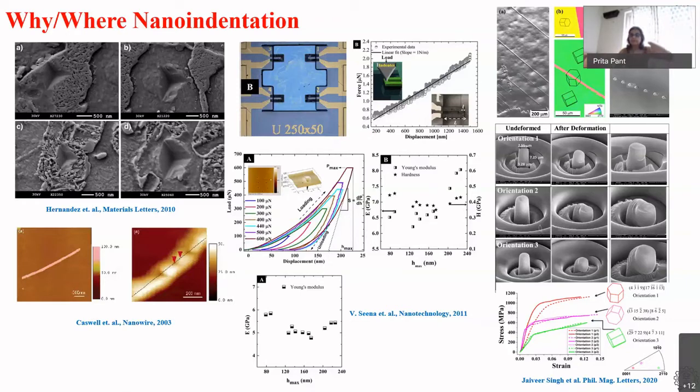film of it. Now this film, it's not free hanging in air. Okay, so you make a film on top of something. It could be a glass slide, it could be a piece of silicon. You make a film on top of it and you indent from the top. Okay, and these are some examples of indents where you apply a load and you measure the displacement again, except that you load, hold it at the maximum load, and then you unload it and you do some analysis on this unloading, which is where we are headed today.